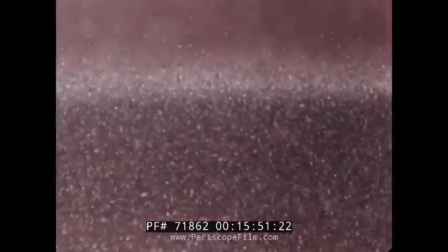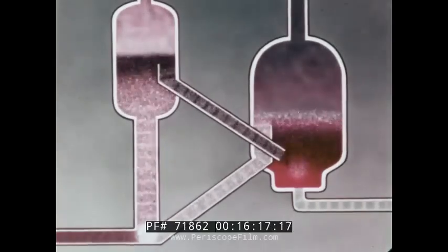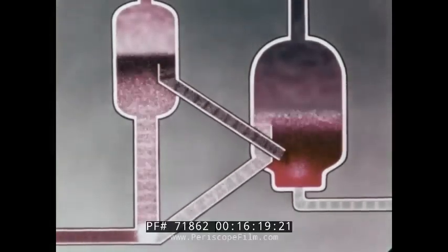Before long, however, carbon forms on the catalyst, clogging the openings. This reduces the working area and makes the catalyst less effective, so it has to be cleaned. It's fed to a regenerator, where the carbon is burned off. The burning also heats the catalyst back to its working temperature, and it's ready for use again. This is the cycle of the cat cracker.